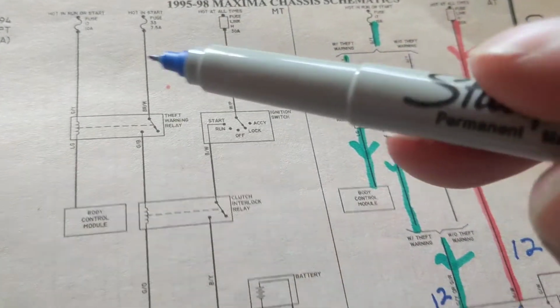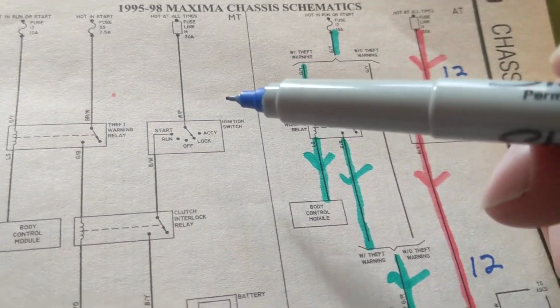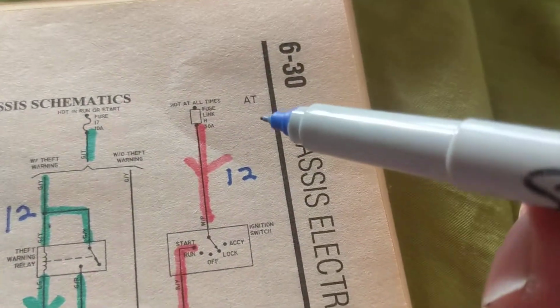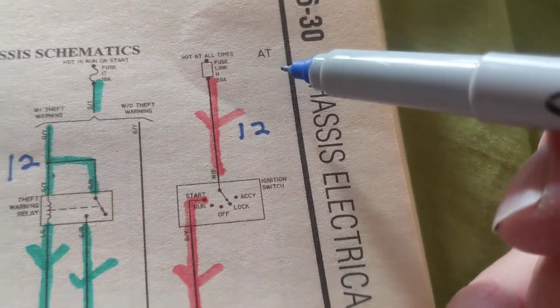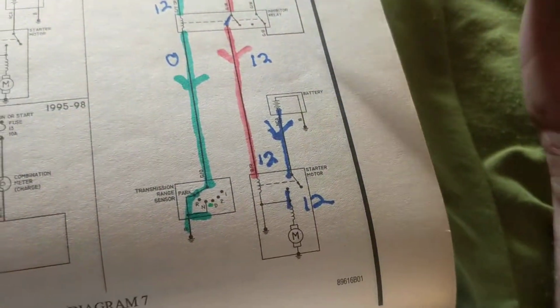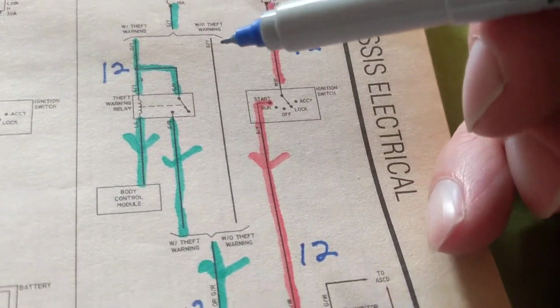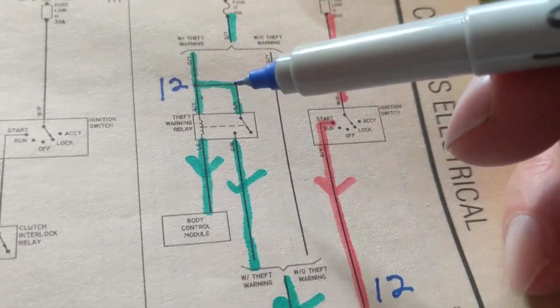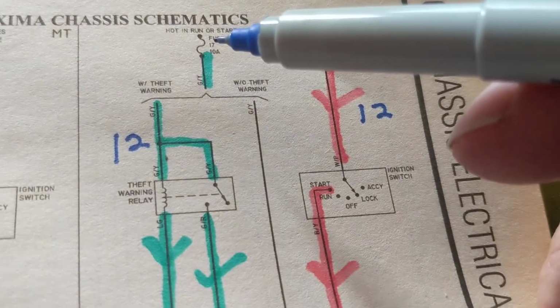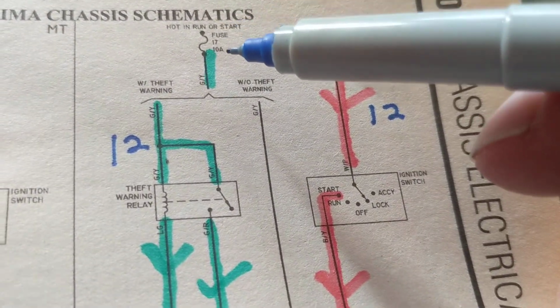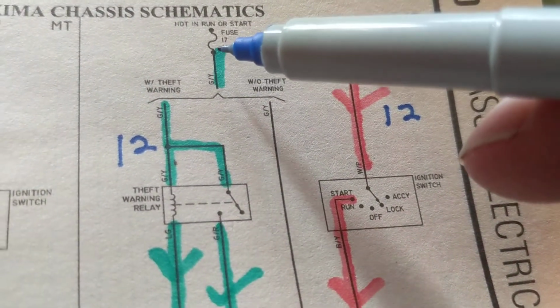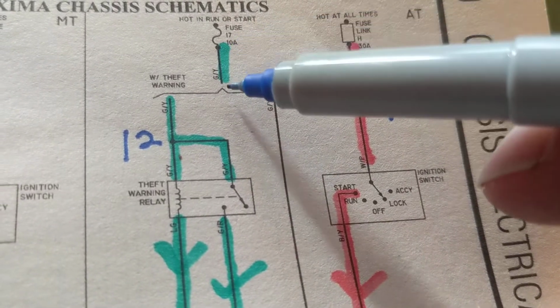So this part of the schematic is manual transmission. No, we want to deal with automatic transmission. Go up here, AT, automatic transmission. That means we want to deal with this part of the schematic, not this. Now, relays, we just talked about how they work. Okay? We come here to the fuse. We know 12 volts is present. When we come over here to the other side of the fuse, current flows.